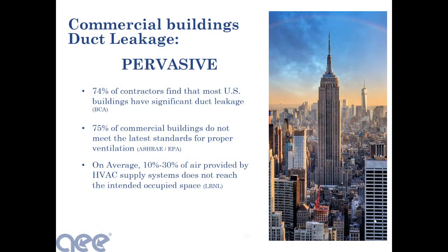We know that the problem of air duct leakage is pervasive. In fact, in the last 10 years, we have learned so much about this problem that we didn't know. If you talk to a building commissioning engineer, they'll tell you that 3/4 of the time when they go into a building and try to commission it, they're trying to get it to balance. It won't balance because the air ducts leak too much.